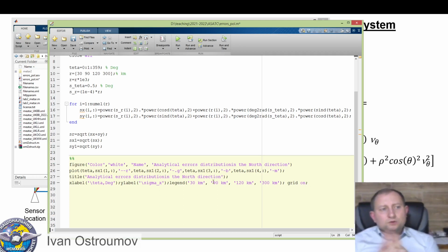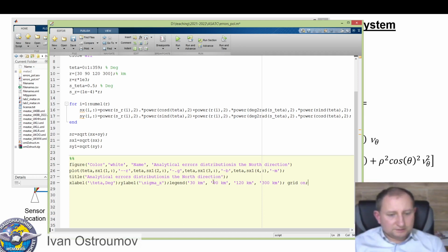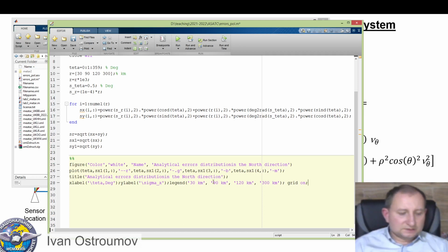However, it is also quite important that usually Matlab tunes the zoom for the x-axis not precisely. This is due to applying a scale in the x-axis. That's why it is much better to specify xlim, to specify limit values for the x-axis.